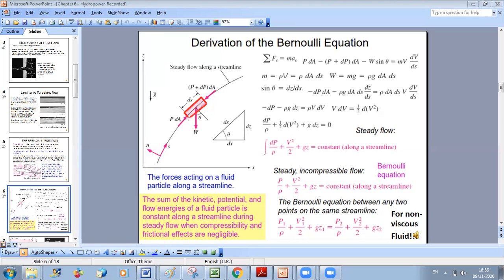I apply the energy equation, because in your energy equation, you take into account all forms of energy. Because when you put work and heat, you take into account possible losses, okay? Because you can lose heat or you can lose work, for example. So in this case, if I don't have application of Bernoulli, I can go to the general rule, which is the energy equation, which we used, which is the first law of thermodynamics. So the first law of thermodynamics is always applicable, while Bernoulli equation is restricted to cases where we can neglect losses, we can neglect viscous effects.